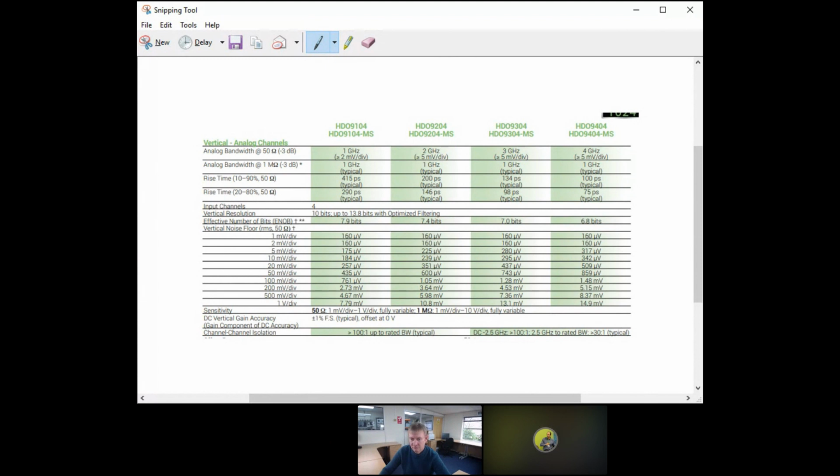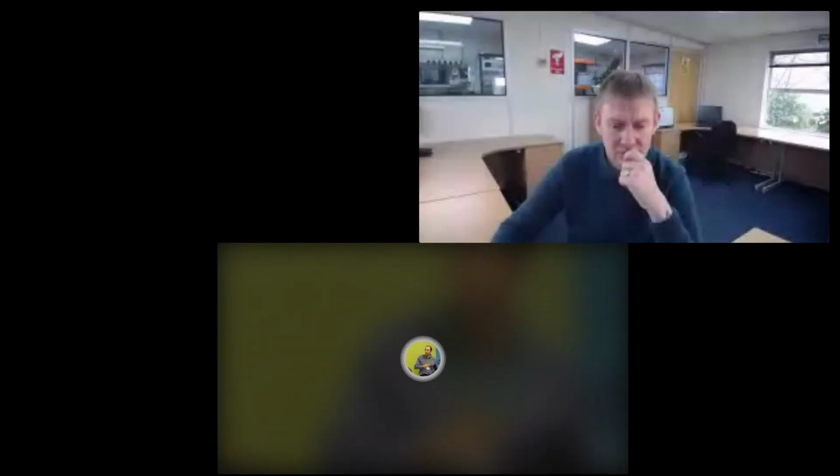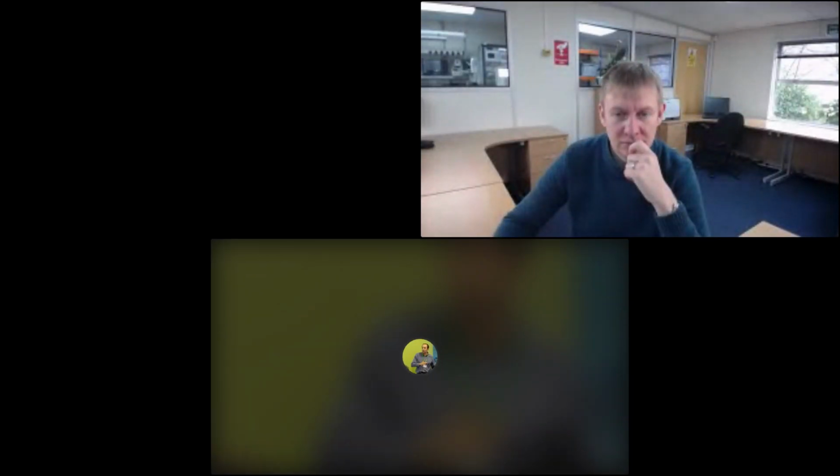Yeah, I agree on that. And then sometimes when you want to measure things, you have to be sure that you are measuring the right thing, that you are not measuring noise, that your scope is good enough, that you have filters. Yeah, exactly. Saturation is an issue: if you want to characterize the drain source voltage transient and you don't care about those millivolts, everything is okay. Yeah. But if you care about those millivolts, you need that circuit.